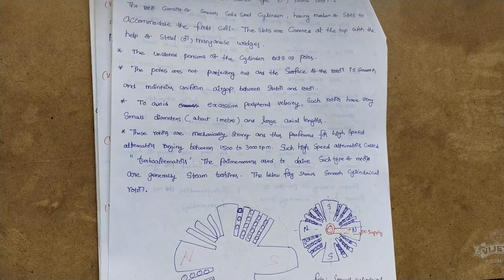As you were told, in single layer winding, the number of slots per pole has only one coil side per slot. In double layer winding, there are two coil sides per slot, a top layer and a bottom layer. Assume these are the slots, and the conductors are laid in the top layer and bottom layer. In a multi-layer winding, n conductors and m coil sides will be present. If there are two coil sides per slot, one at the bottom and another at the top, it is called double layer winding.